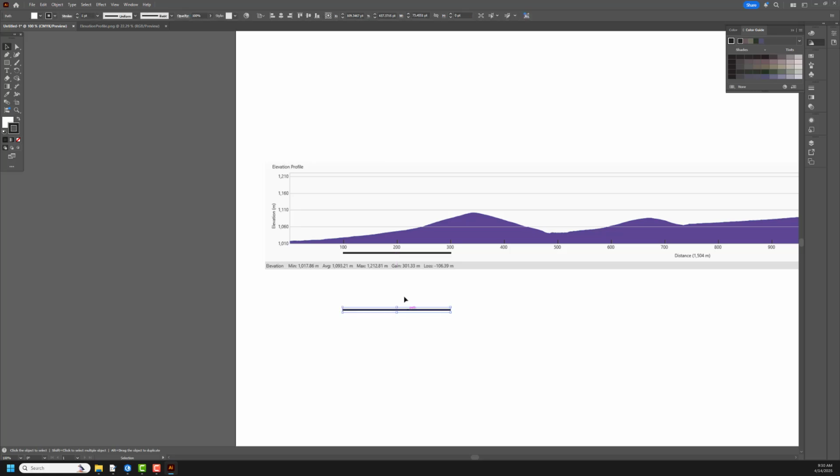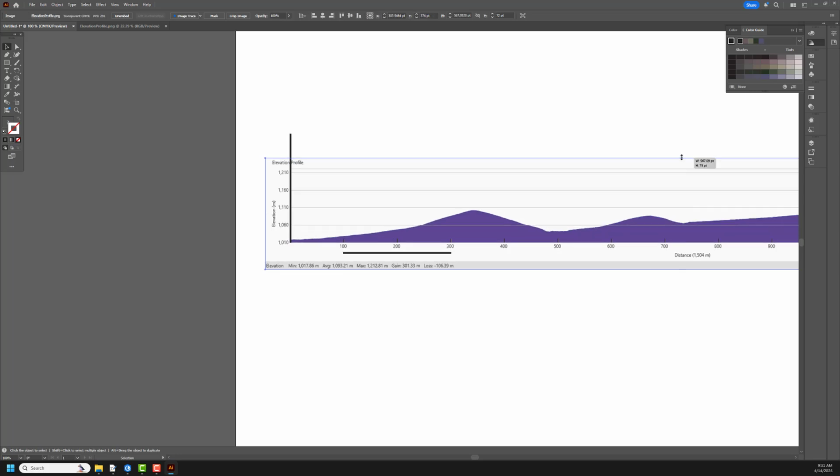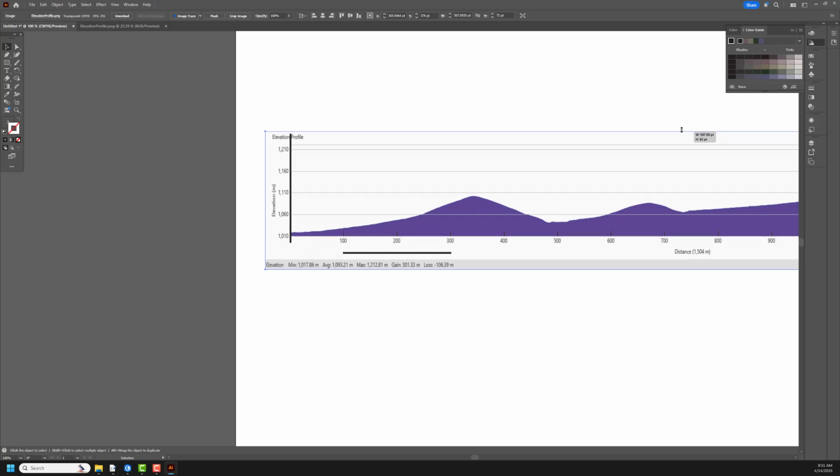So this next one here, if you click on this symbol for rotate, I can rotate it if I grab it, but hold the shift button down, so it only rotates 90 degrees. So go back to the V tool, put this over here, so we know the bottom's at 1010 and the top needs to be at 1210. So now if I click on graphic and I don't hold the shift button down, I can drag this vertically and stretch it. So I've got it.